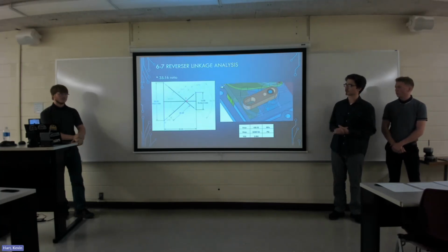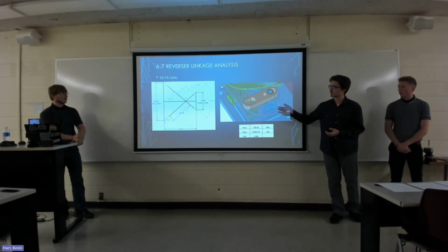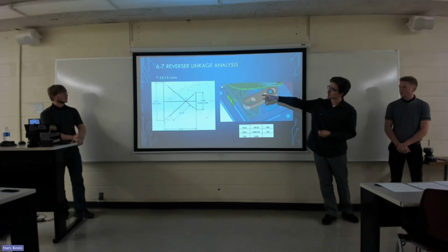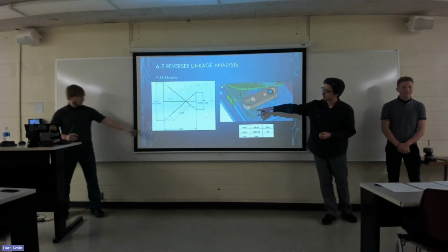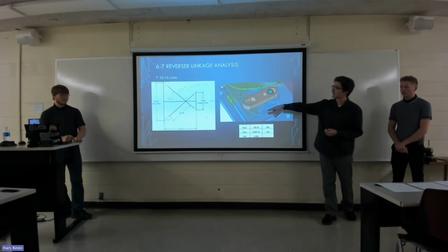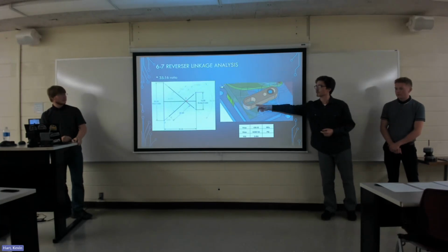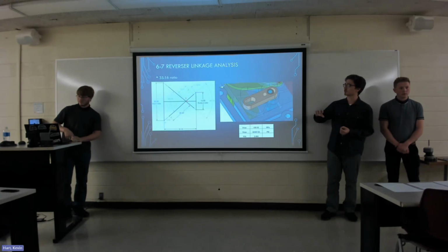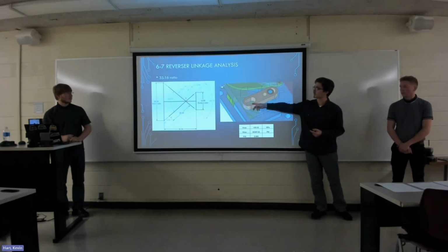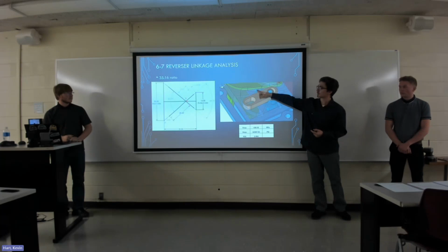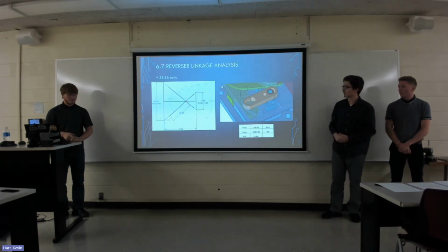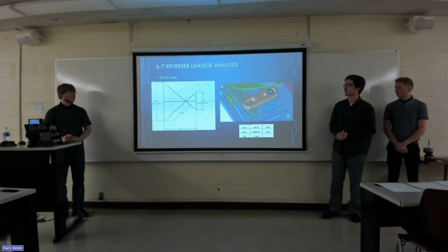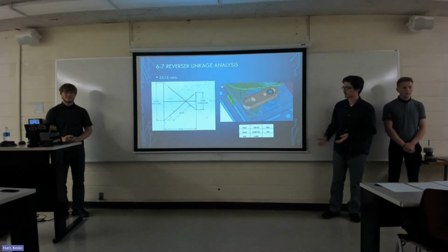On the left, we have another linkage synthesis with 35 millimeter input, 16 millimeter output. If you could briefly see the 2.94 millimeter and the 6.43 millimeter construction lines right at the end, that is the distance of the slots right here for the input, and this is the output. So we'll have the rod going from the driver interface straight connected here in the slot, and it will just pivot along this lever. And right here on the bottom, we have the Hertzian contact stress. For this material, we used 4340 steel, and this resulted in a factor of safety of 2.4.